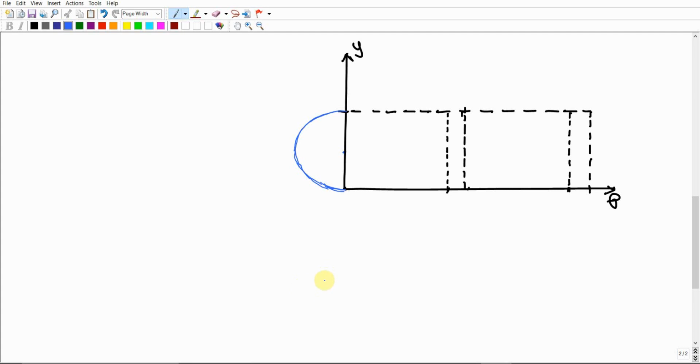Then you're going to break it down, as we discussed for the simple harmonic motion, into 6 sectors. If you divide 180 by 6, this gives us a 30 degree angle. So your objective is to use the protractor that is already traced over the Aristo triangle, or a separate protractor, it doesn't matter, and measure an angle from this vertical line from this center point. Measure the angle starting from this line going in this direction, and you end up with 30 degrees. Measure from this point and draw a very light line. This angle should be the 30 degrees that I'm talking about.